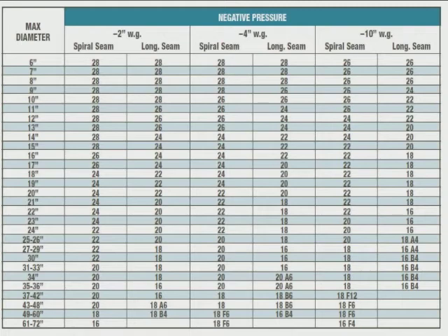Okay, so next we're talking about the SMACNA round negative pressure duct chart. This is available to everyone, but just so you know how we do it, we use negative 10 inches for our welding and vehicle exhaust. That's where we're most comfortable when we're designing ductwork. If you need higher negative pressure, maybe for abrasive applications, you can refer to the SMACNA Industrial Duct Construction Standard.